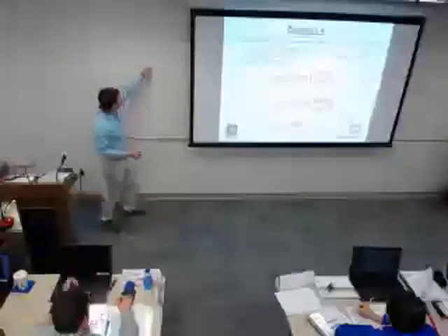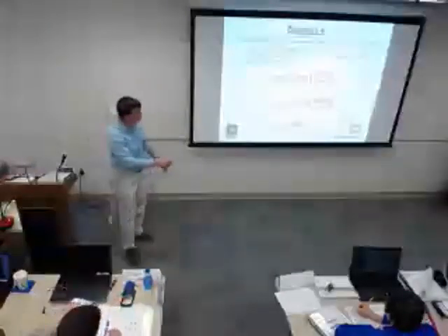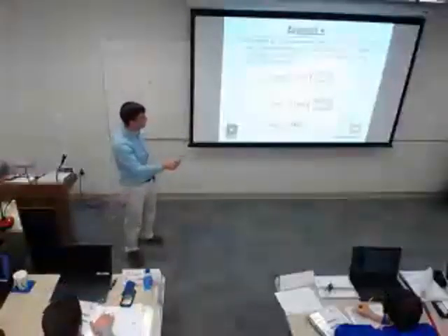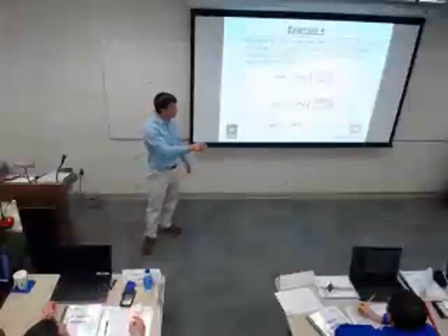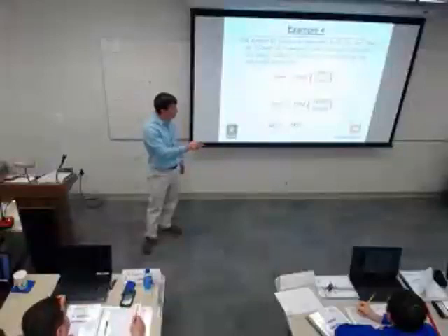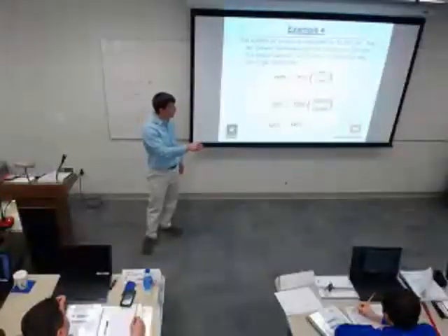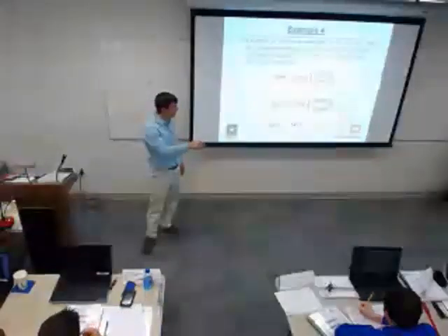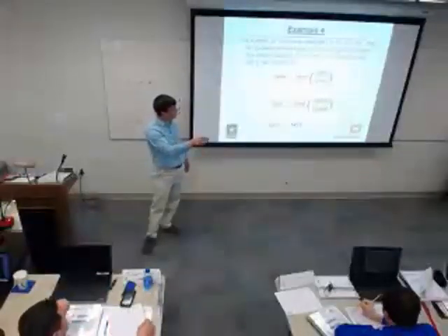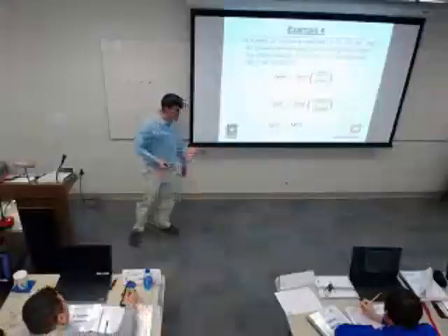Plugging those in, starting with my base equation, I wanted to solve for RPM2. Just multiply both sides by RPM1. That's how I got to here. Going back again, what I knew was subscript 1. I measured 30,000 CFM and I measured 1250 RPM. What I want to get to, my design, was 34,000. Plug those numbers in. I need to change from 1250 RPM to 1417 RPM.